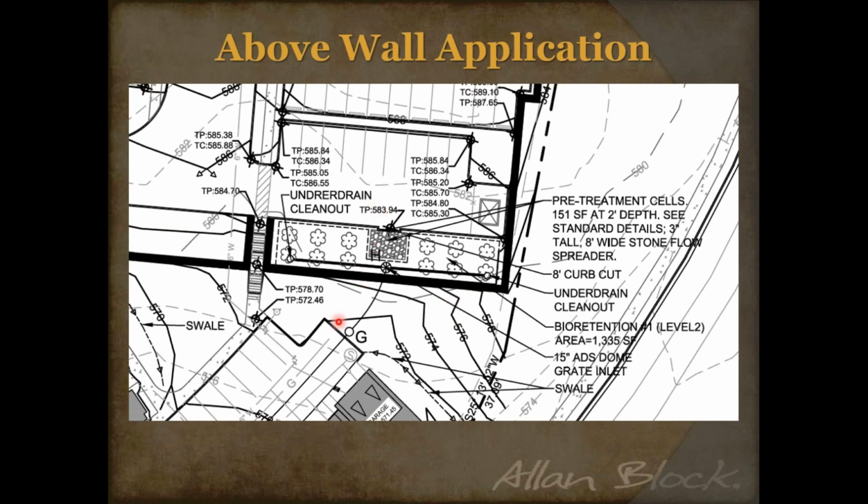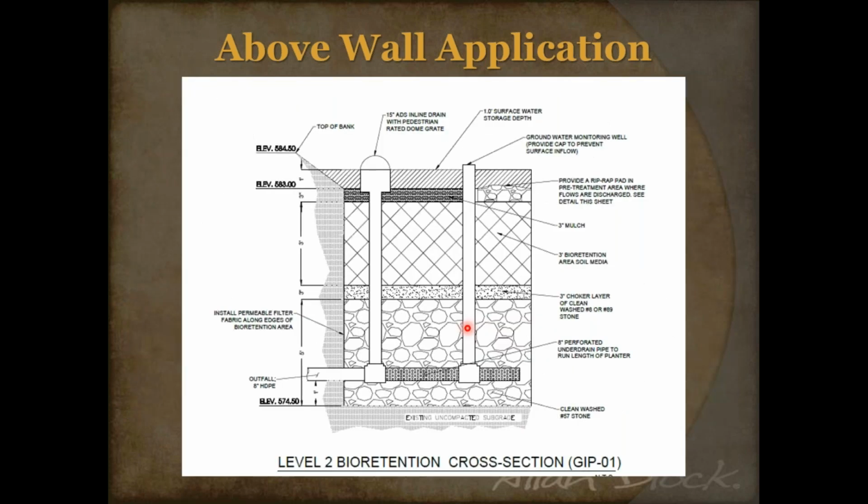So here's a smarter move, and one of the things we talked about with the site civil engineer was, okay, can we have the retaining wall here and hold up the parking lot, then bring in your inlet pipes and stuff to your bioretention pond that's below the wall? Is that a possibility? How can we regrade some of this and look at that? Because if you look at the concept detail that they had, here's where the flow is coming from. It's coming right from this area. We've got some riprap and stuff that is supposed to slow the discharge down. This hatching right here is kind of showing the potential high water mark. And you got the overflow and everything in through here too.